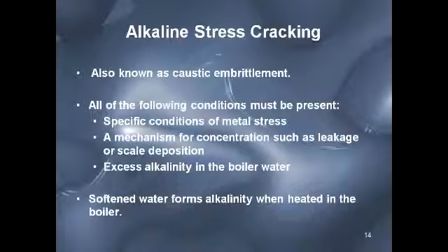Please also note that the use of softened water can lead to levels of excess alkalinity in the boiler, increasing the likelihood of this problem. Note on this picture that's coming up the intercrystalline cracking. It's very identifiable when a boiler is inspected after this type of corrosion occurs.